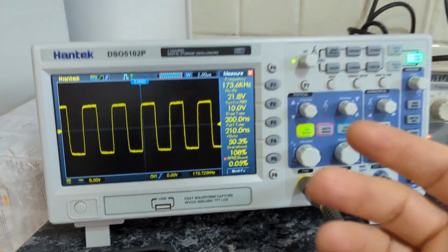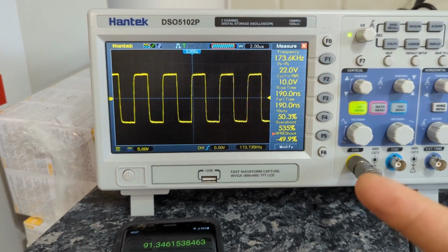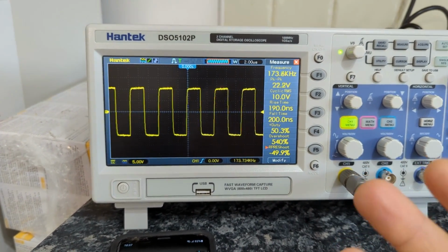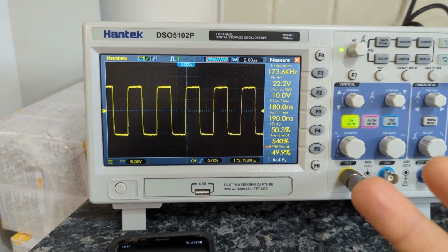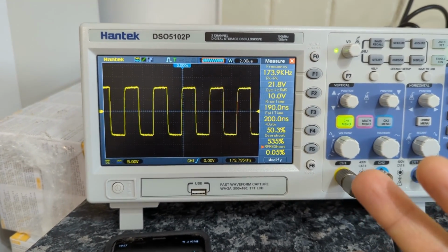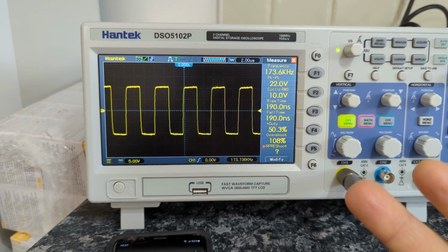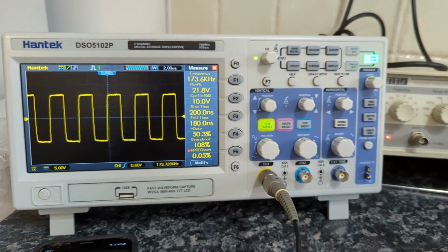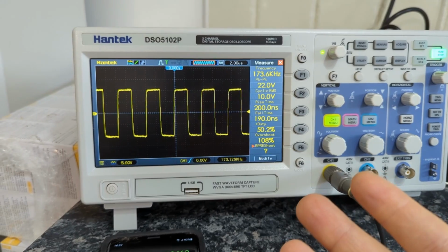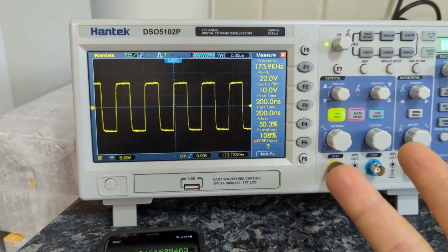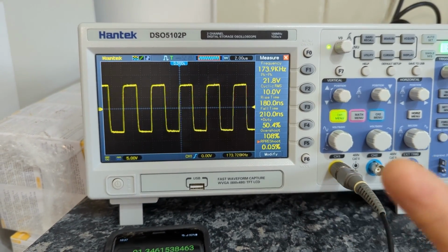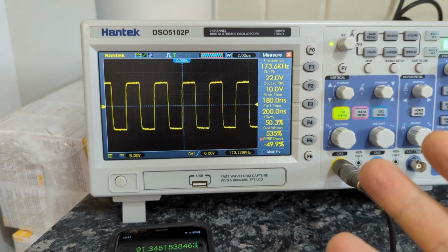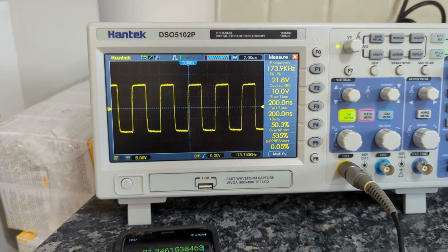Then I'm going to try to measure the amplifiers at maximum voltage just before clipping, just to see how much that amplifier is capable of, because again, the slew rate depends on the voltage, not on the frequency. So it's going to be two measurements. One is just for comparison at 10 volts RMS, and the second one at max power, just to see what the amplifier is capable of.